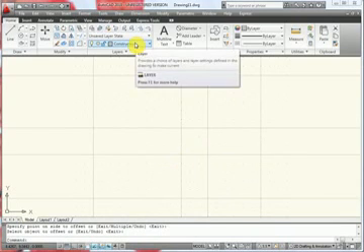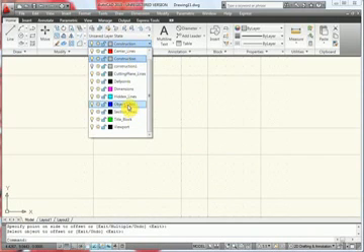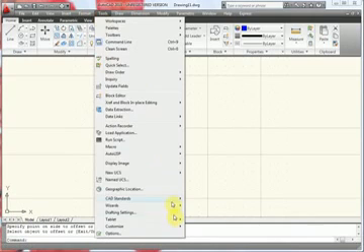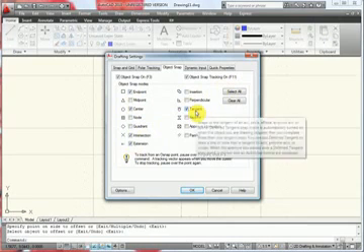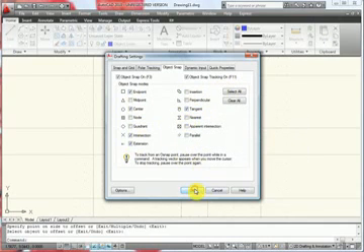My next step here is I'm going to switch to my object line, and now I'm going to go to Tools, Drafting Settings, and go over to Object Snap. With Object Snap, it allows me to snap my cursor to specific locations in my drawing, as long as Object Snap is turned on. Generally, when I draft, I'll have the majority of these on. However, sometimes it can become a nuisance, and it'll snap to locations you don't want it to snap to. So for now, we're just going to have the endpoint, center, intersection, extension, and tangent turned on. Once you've done that, you can press OK.